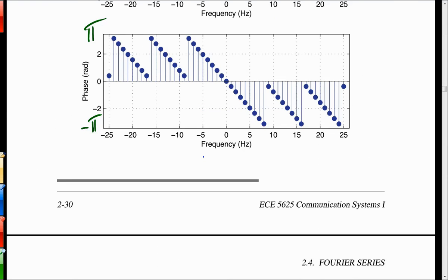But if the phase was steeper, well, whenever the sinc function jumps as well, then you get an extra kick of plus and minus pi. So this picture is actually not showing you the most complicated case. There's two things that can make the phase jump. One is just the linear slope coming down like this and needing to wrap by 2 pi, and then there's the other one that makes it wrap by pi.